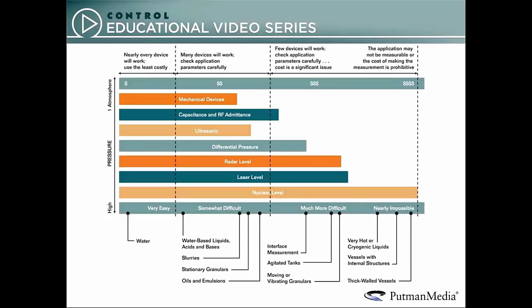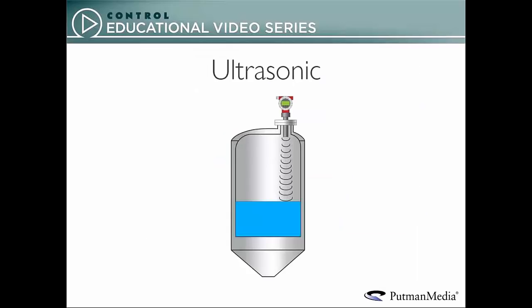Ultrasonic gauges are also quite versatile and offer good value. Ultrasonic gauges calculate level based on the time required for an ultrasonic signal to be reflected from the liquid surface. They and the other time-of-flight gauges coming later use signal conditioning and computing power to adapt to specific liquids, solids, and vessel conditions. They're seeing increasing applications as the cost of signal conditioning and computing has come down.